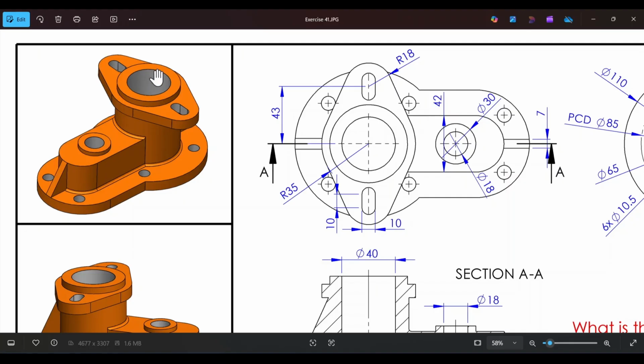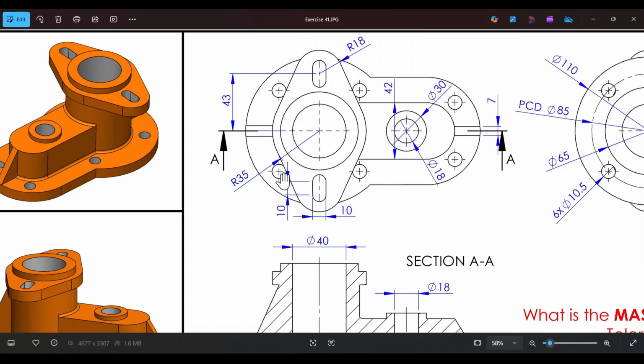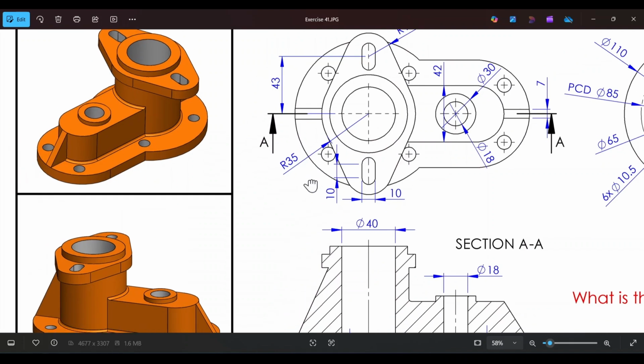And finally, we're going to work on creating these two central bosses, boss number 1 and boss number 2, along with the openings shown here on the top flange, but also along the cylinders that we just created, okay? And of course, we also have these mounting holes on the top base flange, and it's pretty easy to create. You just draw a number of circles, position them correctly relative to their centers, and then use the extrude cut tool. It's not that difficult.